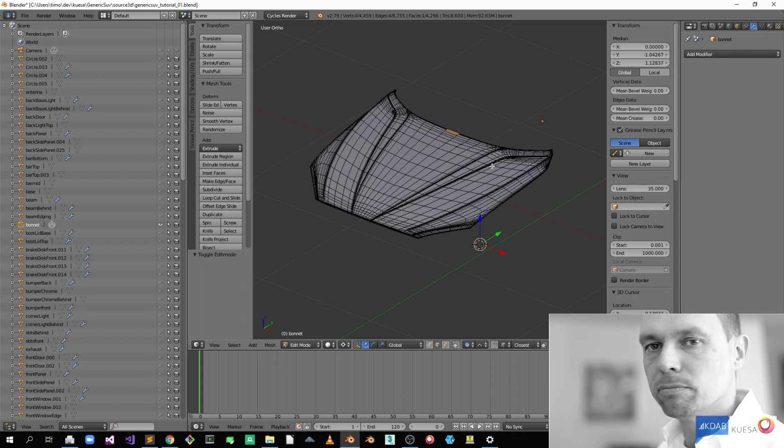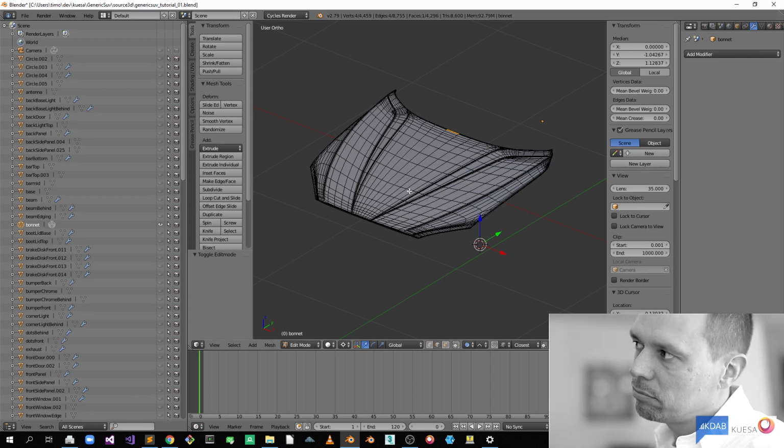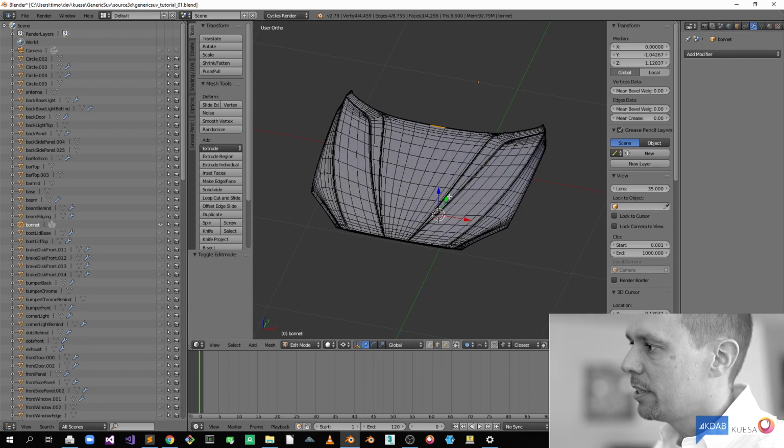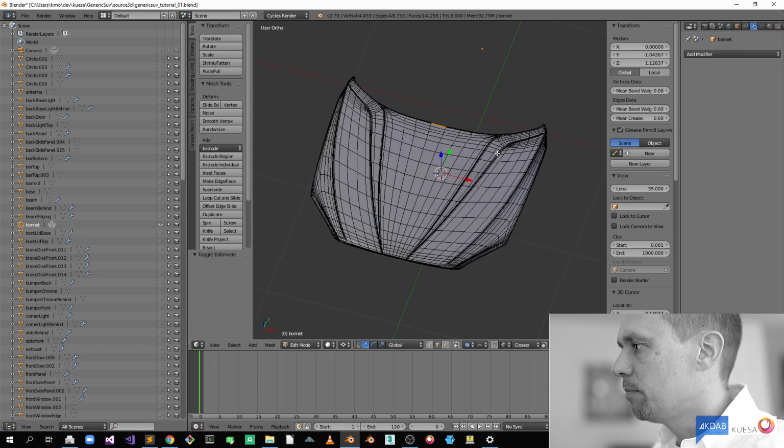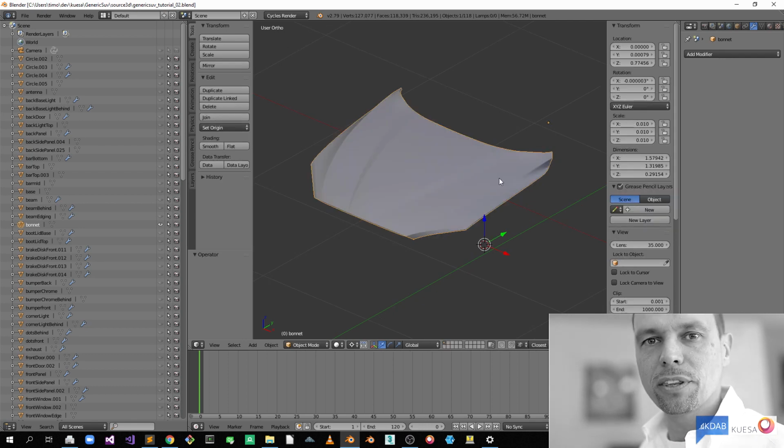We could reduce even more here, but we went from slightly below 4K to slightly above 4K, and keeping almost the same face count, we now managed to get a much better mesh for reflections, so all the quads are in a much better aspect ratio. You don't see the polygons here anymore, and I think we are good to go to use this for real-time 3D now. There's one thing I wanted to show you.